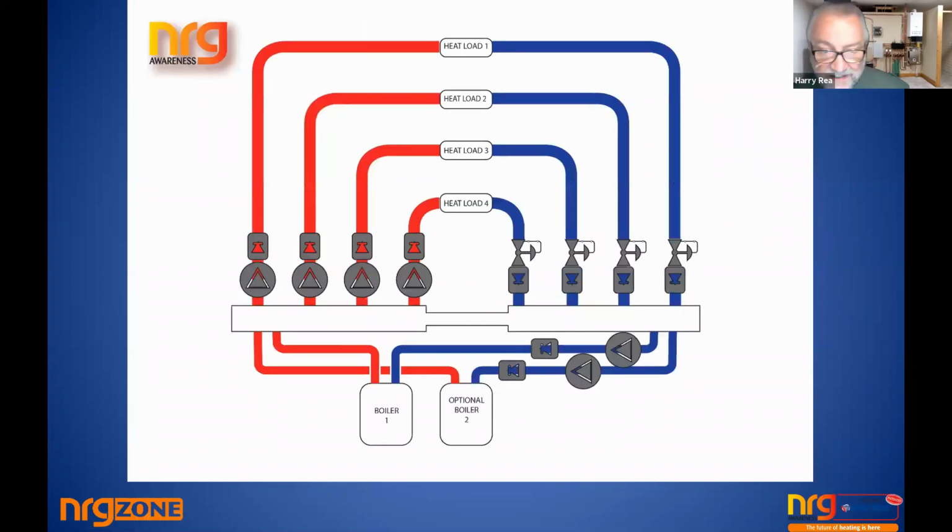If you have the exact same system and you turn it facing upwards, like again in America, you have a lot of boilers in basements. But of course, if you're in a two-story house and you've got a circuit upstairs, you have to prevent the heat rising up. So you're going to use a check valve in front of it. But you also could have drifted heat from the return, just like a solid fuel boiler works. You have a gravity circuit that could potentially go up through one pipe circulation and feed backward into the radiators.